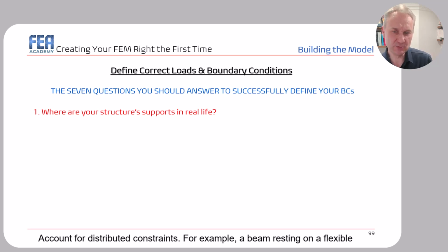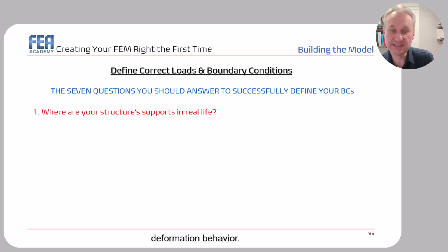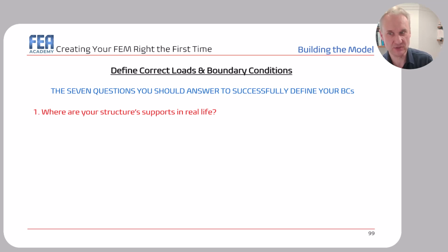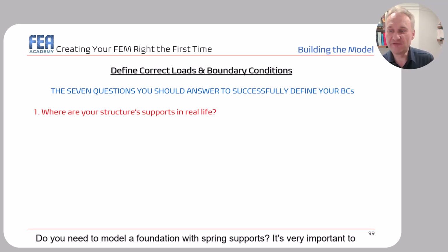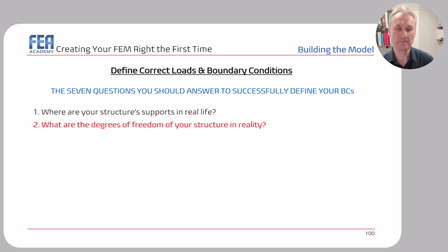Account for distributed constraints. For example, a beam resting on a flexible support should not be modeled with a rigid fixed constraint, as this would alter its deformation behavior. Check for real-life flexibility in supports. If the structure rests on a surface, is it rigid or elastic? Answer this question: do you need to model a foundation with spring supports? It's very important to answer this question in order to define proper boundary conditions.